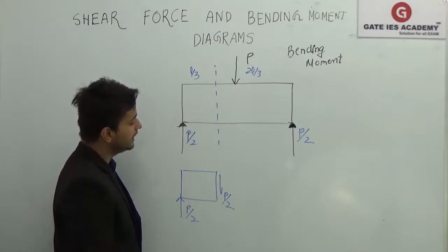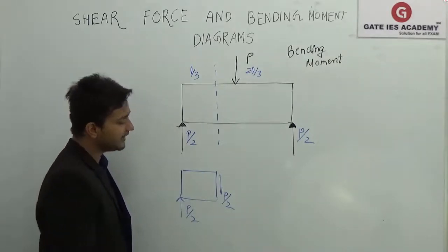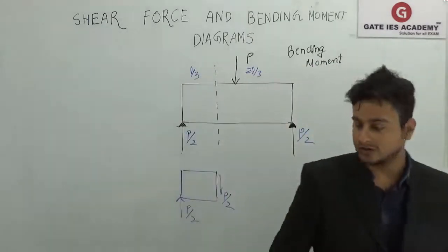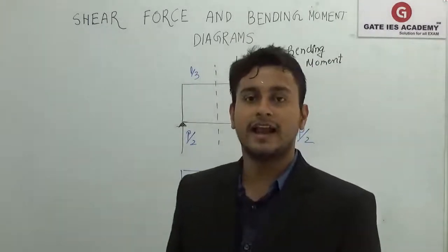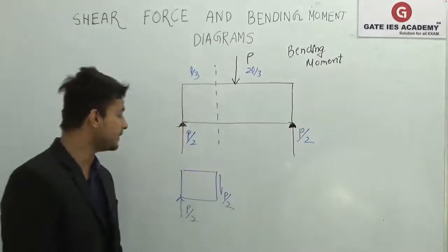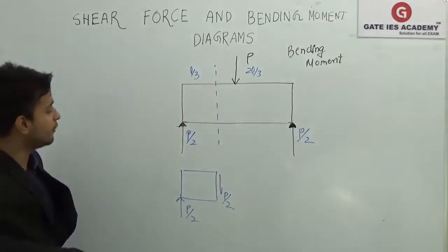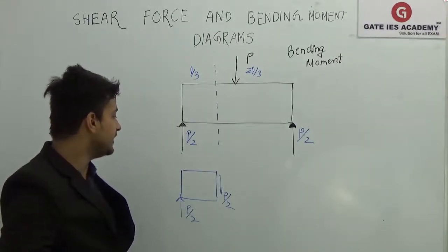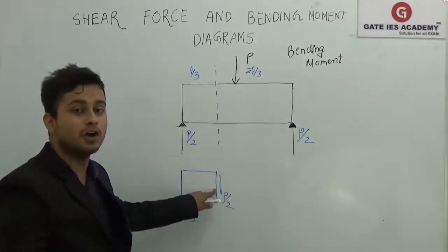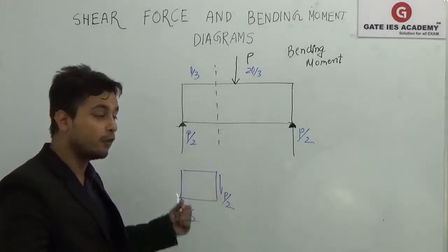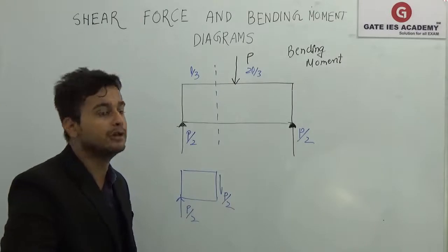Okay, very easy. Now, but do you think this is a balanced system? The last problem which I took was like this only, and there was a simple mistake I was making, I was not focused a little bit. But now, can you tell me what should be the focus over here? The focus is that the system is not in equilibrium. Why? Because this is in force equilibrium but not in moment equilibrium.